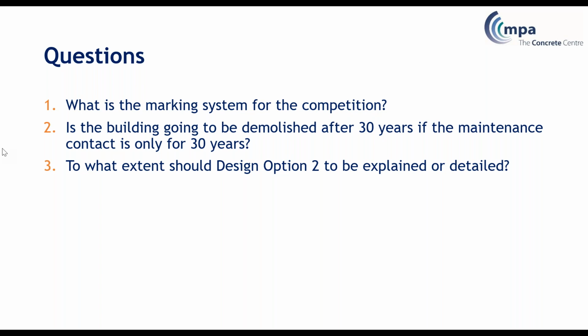Are there any full design guides for precast? We don't have them. There's a useful book by Kim Elliott, if you can find that in your library, on precast design. And the hybrid guide that you've got is quite useful, and the offsite construction one also has quite a lot of stuff in there. But no, there isn't a full design guide for precast. Much of precast or hybrid design is the same as in situ design. It's from Eurocode 2, so the Eurocode 2 stuff works.